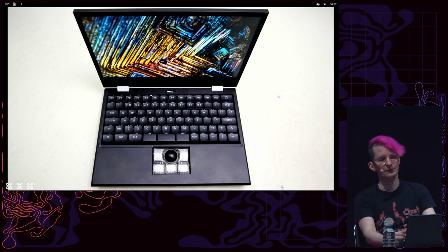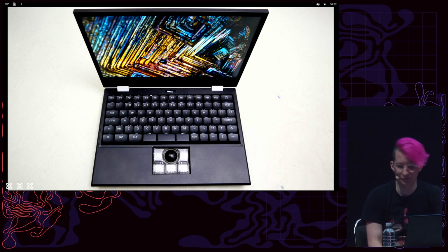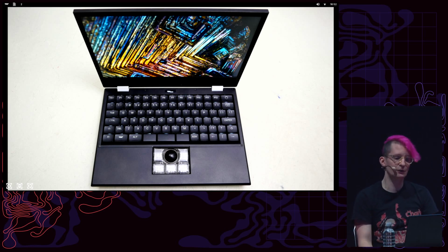For Reform 1, we still ship the DIY printed caps, but there were many issues we encountered in real-world tests with the laptop that we decided to completely redesign the laptop and also upgrade the processor to IMX8M. Although it was binary blob-free and had awesome documentation, including the memory map, the 32-bit IMX6 seemed too slow for a daily driver, and I made the difficult decision to switch to the new processor, the 64-bit IMX8M, which introduced a binary blob, so a closed-source piece of firmware, for its memory controller.